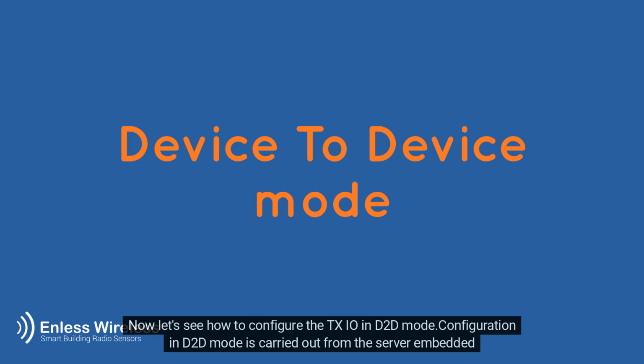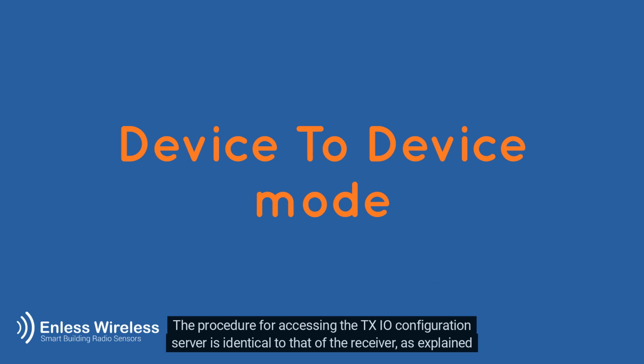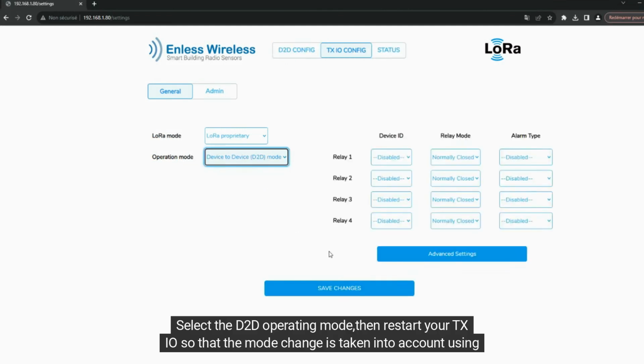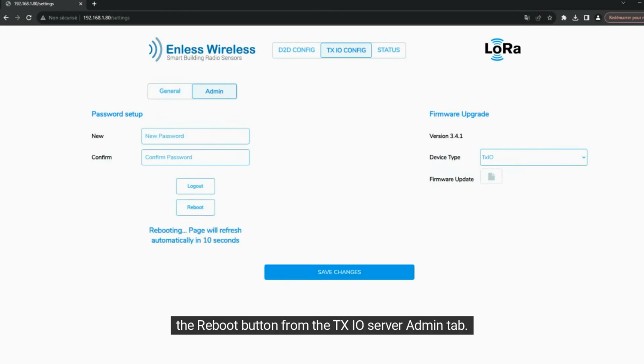Now let's see how to configure the TXIO in D2D mode. Configuration in D2D mode is carried out from the server embedded in the TXIO. The procedure for accessing the TXIO configuration server is identical to that of the receiver, as explained at the beginning of this video. Select the D2D operating mode, then restart your TXIO so that the mode change is taken into account using the Reboot button from the TXIO Server Admin tab.